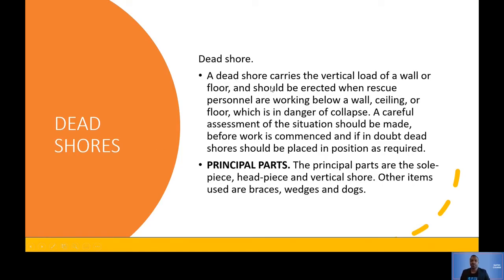A dead shore carries the vertical load of a wall or floor and should be erected when rescuing personnel are working below a wall, ceiling, or floor. So really, that's about it. If you're going to remove the bottom of a place, then you need dead shores to support the top part of that wall or the top part of that building. Just remember that it has to do with removing the bottom of the wall.